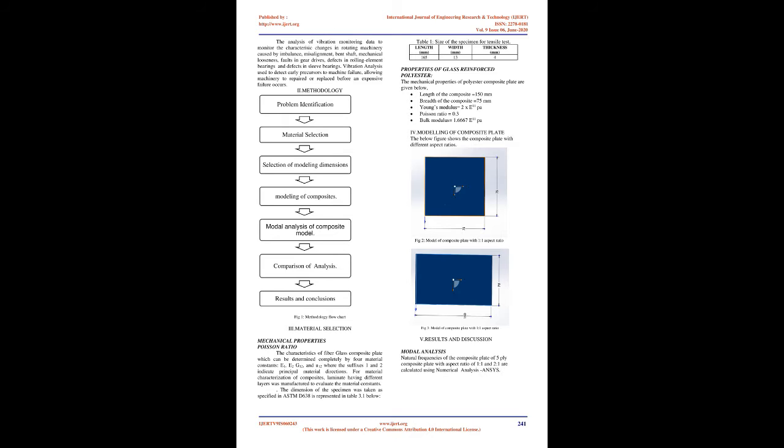Introduction. Glass fibers were prepared using the melt spinning technique. These involve melting the glass composition in a platinum crucible, which has small holes for the flow of molten glass. Continuous fibers can be drawn out through the holes and wound into spindles, while the woven fibers were produced by close arrangements of long fibers similar to the arrangement of threads in clothes. Based on their arrangement, they may be classified as unidirectional and bidirectional fibers. Fiber dimensions and to some extent properties can be controlled by process variables such as the melt's temperature and spinning rate.